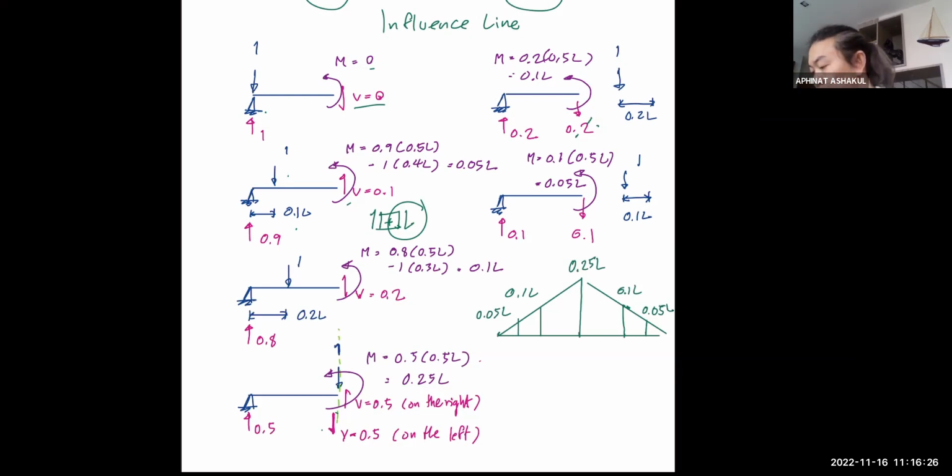So this doesn't look very beautiful, but yeah, it's the influence line of the moment at midspan. You see, the moment at midspan changes its magnitude when we move the load around. The load produces the maximum moment when we place it right there at midspan, and it goes down when the load moves away from midspan as well. So this becomes the influence line of midspan.